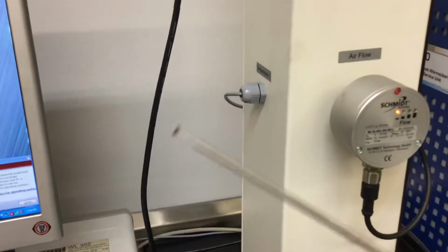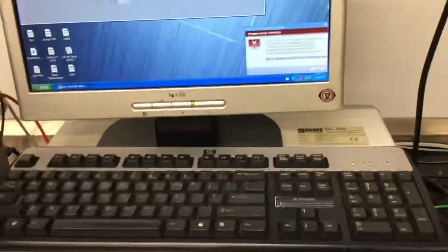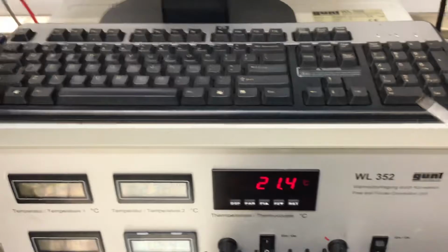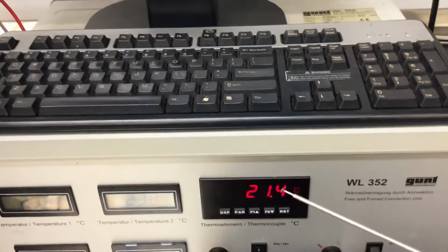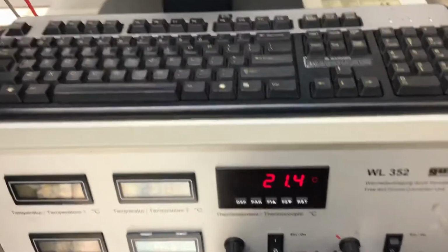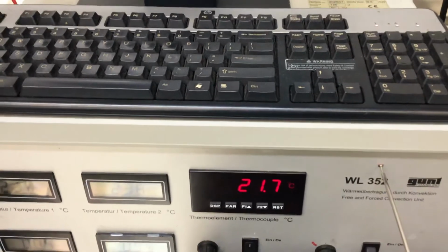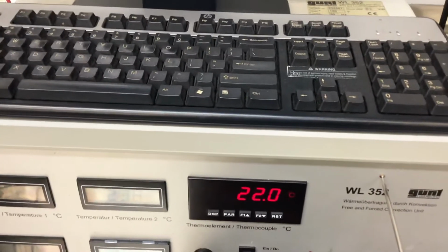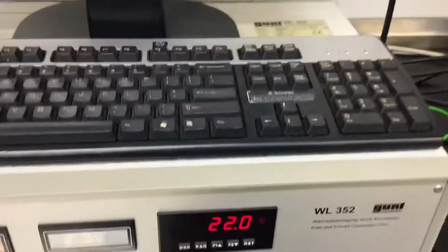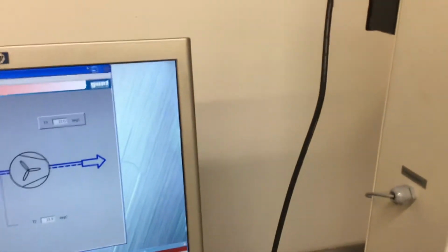So I can show you here, that's a thermocouple that is handheld, connected to this red screen that you see in front of you here. It measures the surface temperature when you have direct contact with it. So you can see now if I contact this surface, it's going to measure the surface that we have here, which is clearly a smaller value because it's very close to the ambient temperature. If I go inside the machine here and start to use the thermocouple,